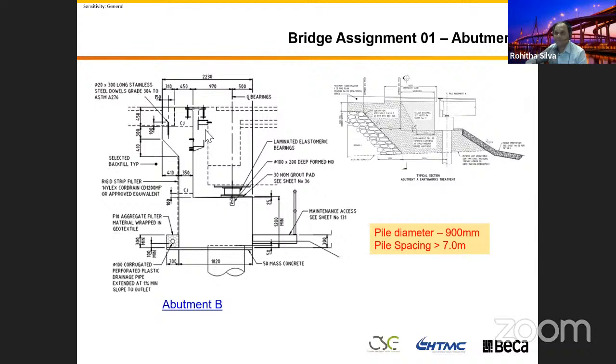You need to have a drainage gutter there, that's the gap, for the thermal expansion and contraction, right? Because this bridge is creeping away, it's mostly governed by this bucket dimension. So that gap plus the thickness of the wing wall will dictate the width of this member.